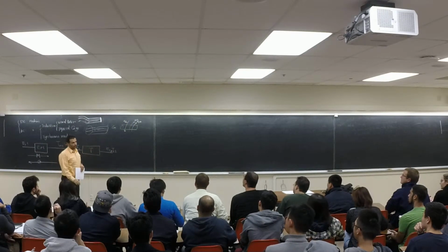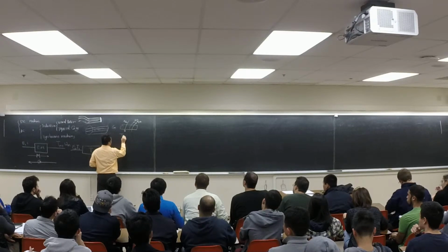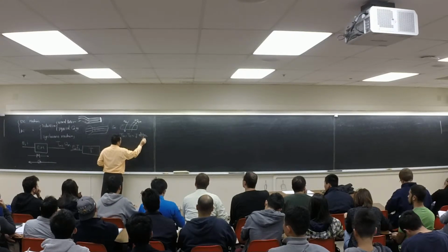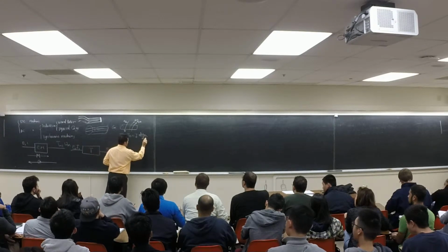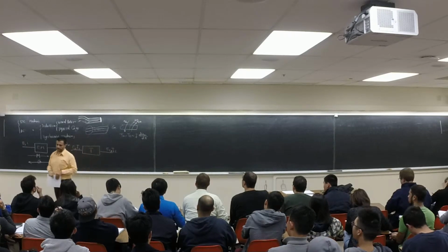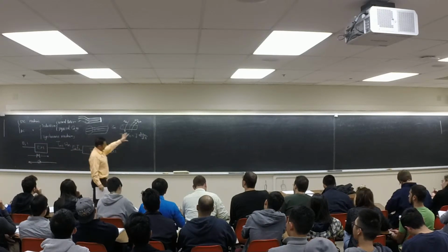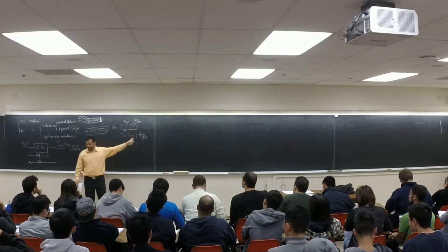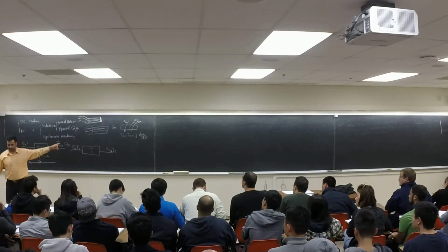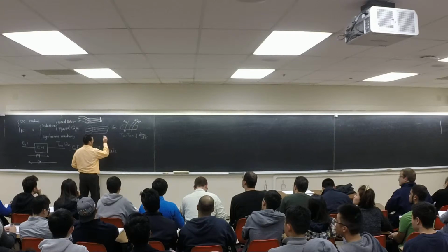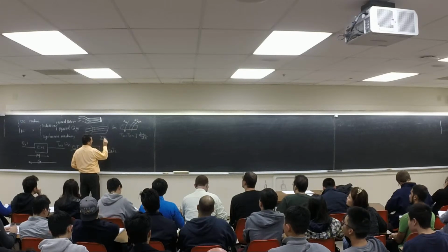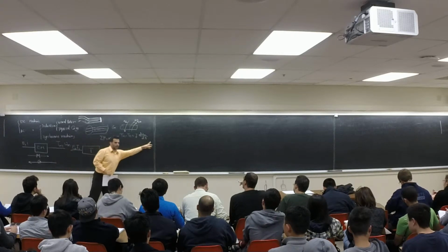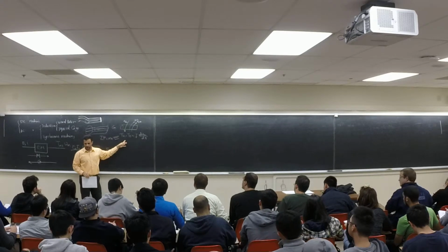If you want to write the differential equation of this system, you say Tm minus Te equals J d omega over dt. This is the angular acceleration. In Newton's law, we said sigma F equals ma. These two rules are the same. This one is for a linear system, and this is for a rotational system.